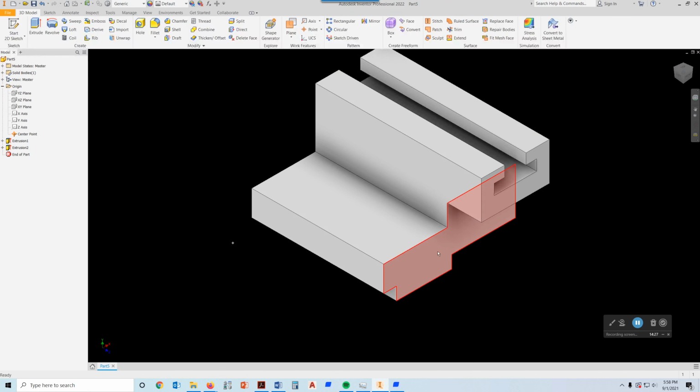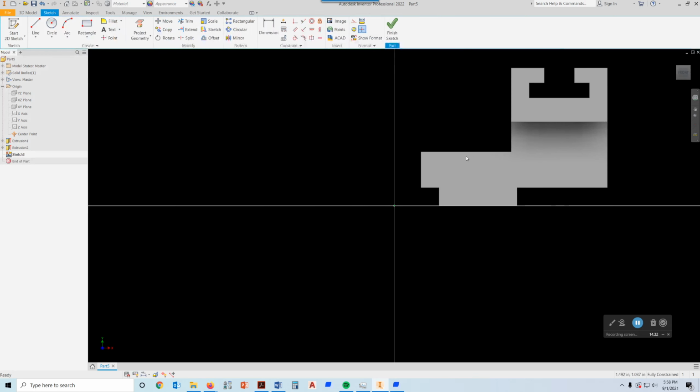All right, at this point, we're going to pick on this plane right there. We're going to make a new sketch. And we're actually going to draw a triangle in here. And what you want to make sure that you don't do is snap right in there. Otherwise, you'll catch the midpoint of that edge. And so you want to just come over into here someplace. Pick on the edge, go to the corner, and then go up, and then come back to that edge right there.